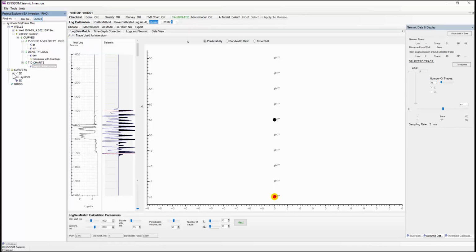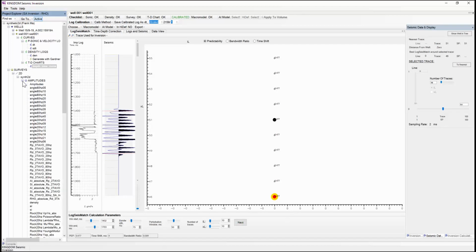And now when we're making our selection with our amplitudes, here we're going to select our RD 3-term AVO, with the density being the 3rd term. Now it's really important here to note that this is only possible with long offset data, but the long offset data is often quite noisy. So it's not just having the angles themselves that enable us to do this, but having good quality information at the zone of interest. And it's very important that you ensure that you have consistent information there that's not too noisy. Now in Kingdom, straddle slicing is good for QCing this far angle data, and this is what we'd need to do before we would have created this reflectivity density volume, like so.